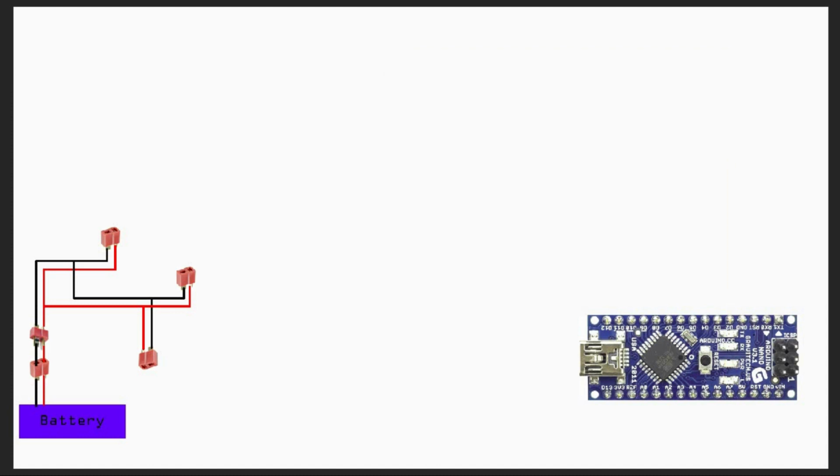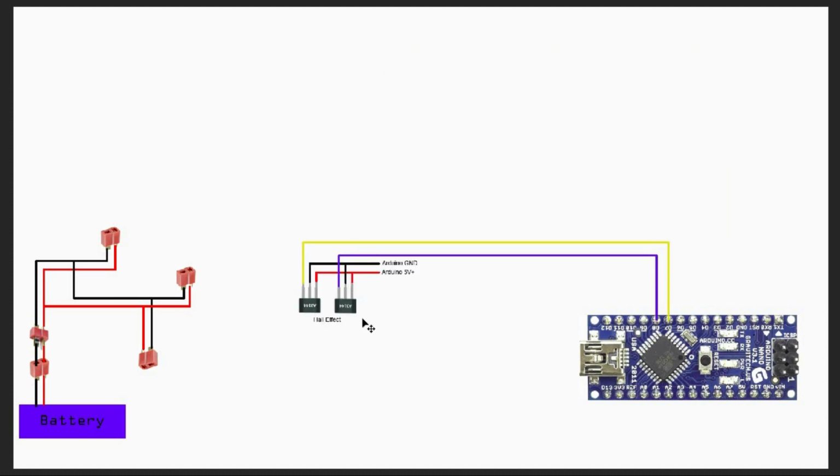So if I were to turn it off, the next one is basically the Hall sensor. For the Hall sensor, I'm just going to use it as an on and off thing. So I have 2 of them. Of course, one of my subscribers told me that some Hall sensors have the ability to gauge the polarity. So you can gauge the strength, connect it to analog read or something like that, and then do even more detection. But for myself, I'm just going to treat it as on and off.